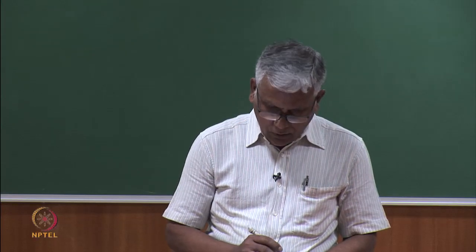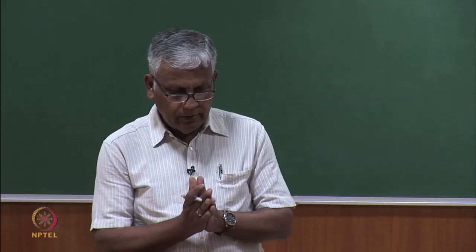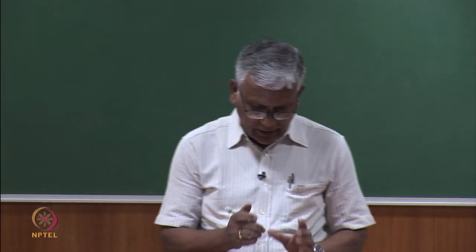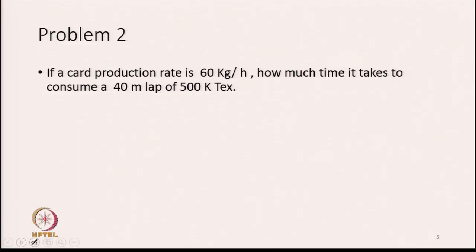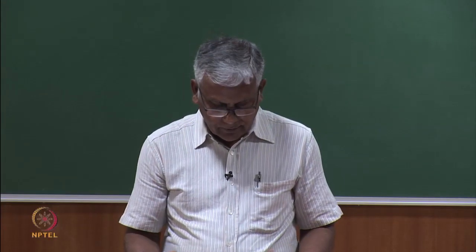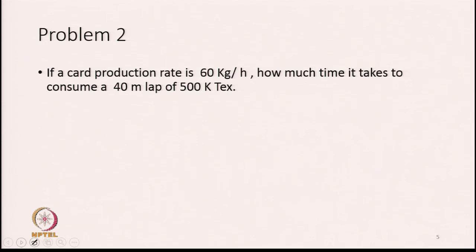From here we go to another problem. Whenever a problem is given, you must read the problem at least twice, and then start thinking how to approach it to get a solution. This problem is very simple. If a card production rate is 60 kg per hour, how much time does it take to consume a 40 meter lap of 500 kilotex? It is a very simple problem.